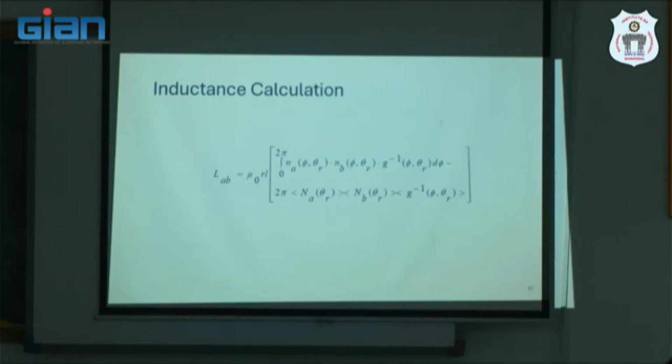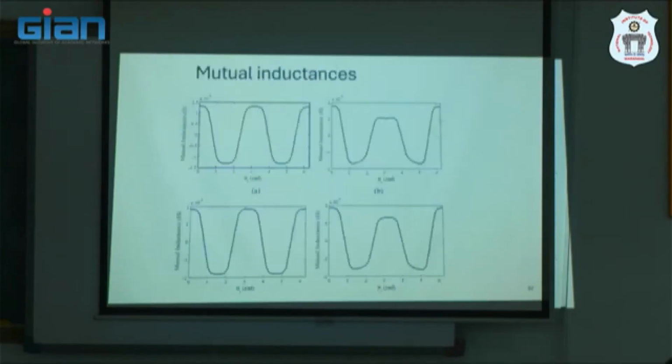I want you to be aware that there is a mathematical technique called the modified winding function approach that will allow you to compute inductances that are rotor position dependent. Okay? And you can see the inductances for different faults. So under healthy condition, the inductance is given here. Under static eccentricity condition, the inductance changes.